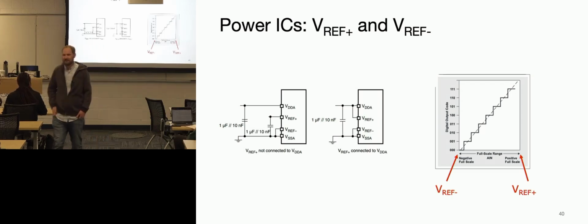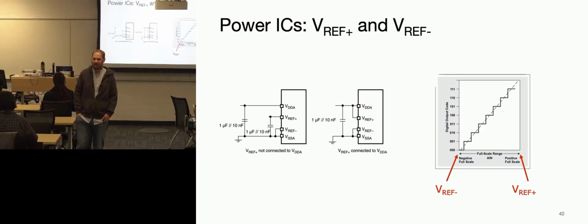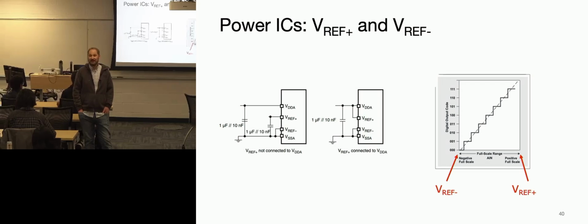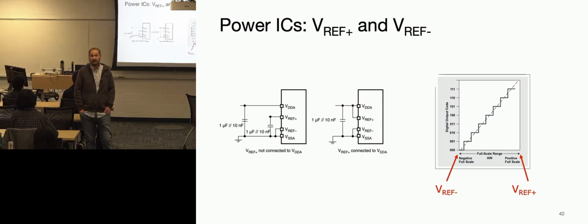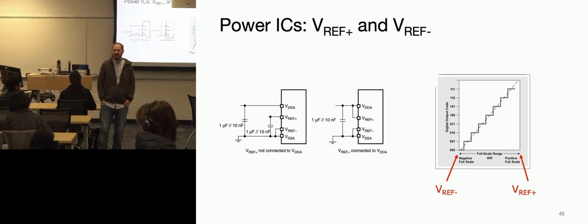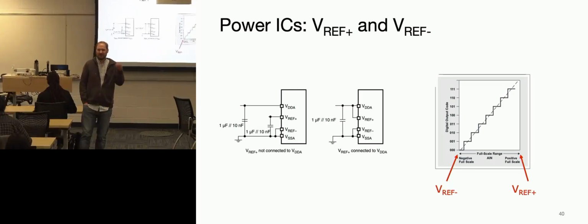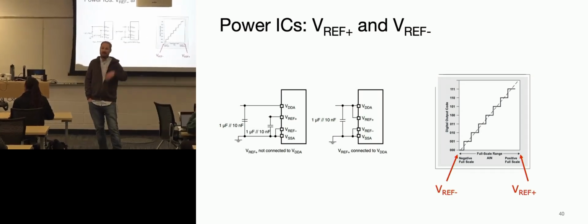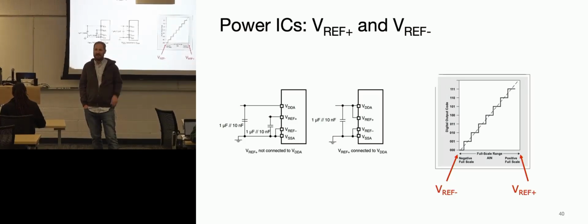When it was 3-bit and 2-bit DACs and ADCs, would a question like that be one where you have to use the minus 1 then? Yeah, I don't think we're too litigious on the homework, but yeah, that's a small number of bits, so it's going to make a bigger difference. In the exam, would we need to use the minus 1 since we would know that it's a small number of bits? Again, I'm not too litigious about this, but if it's like a 12-bit ADC, you can calculate what the delta V is, and it's very, very small, like you're in nanovolts. But when I taught it the other way, then students would come in and say, this data sheet says it's not like that. And I'd be like, oh.